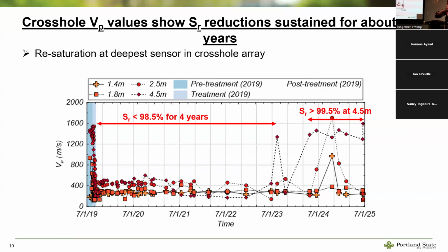We don't see a signal from that up and down in most of the sensors in terms of volumetric water content. Most of them are just steady and reduced. And so like Ed has pointed out, that water table is really, in this case, affecting total stress, effective stress. And so why this happened to go up, I don't think it's the summer versus the winter when it's flooding. I think it's mostly about what's happening in the subsurface for the gradients of the fresh water that's moving through. And maybe it happened in the summer because the gradients are higher, putting more water through in the summer. Maybe it's just the time that it happened.